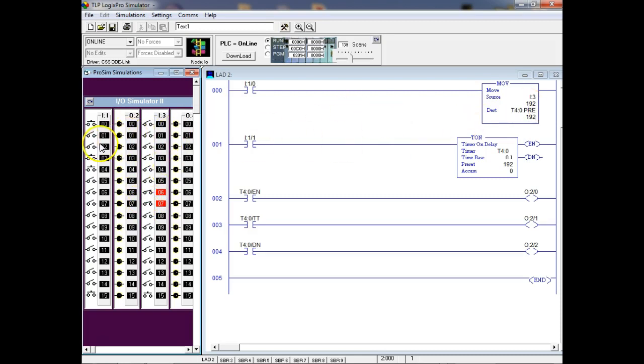And then I'm going to come over here and let my BCD, it's now binary? Well, it never was BCD. My switches were BCD, but when I used the move instruction, it interprets it to be binary. So what was happening was I set my BCD switches to this, and that would be this in BCD. But my move instruction saw it as 1, 2, 4, 8. It saw it as 16, right?